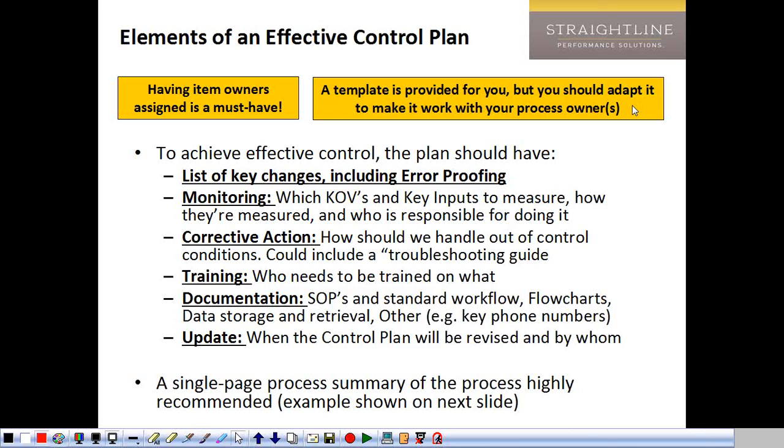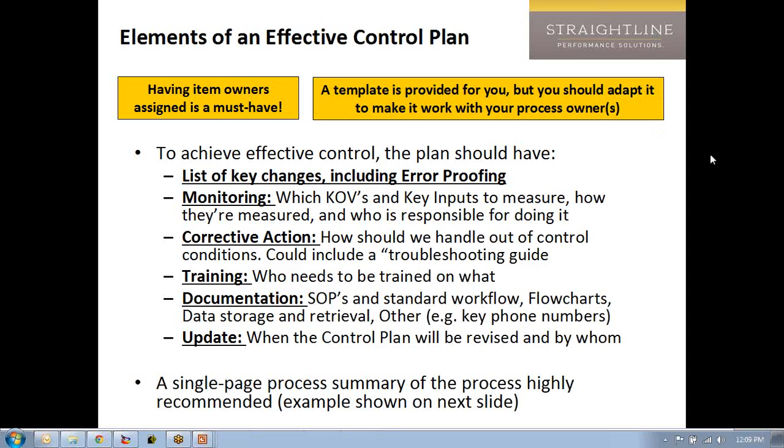I probably shared this with you a long time ago in one of the first lectures, but one of the things that's really important in fiber optics is not to make them tight and neat, because then you create cracks in the fibers and you have all sorts of problems. So people needed to be trained to not do what was the right thing before.